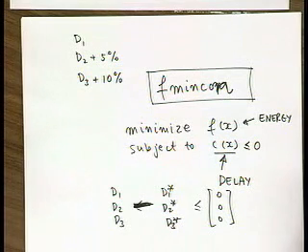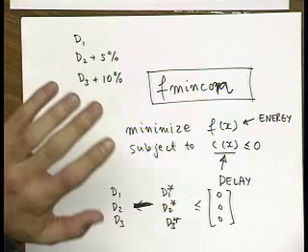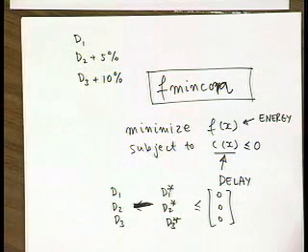Then the final stage, which should take you about half a week, is to plug all this into HSpice and see if you have any difference in results between your hand analysis using that calibrated delay model and your SPICE results, and sort of understand what's really going on there with the signal slopes, with nonlinear capacitances, and all of these things. So read all that in the background material we posted, so that will be helpful.